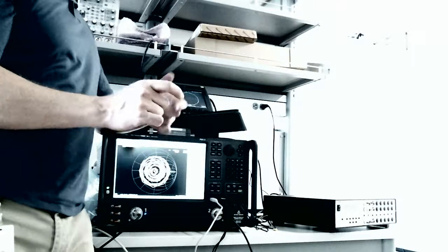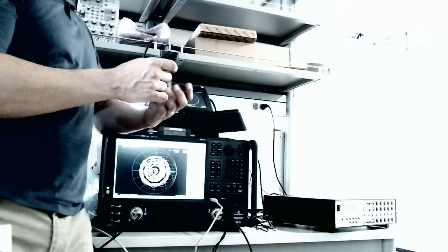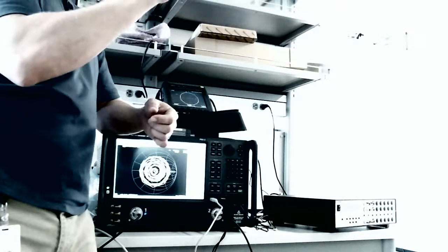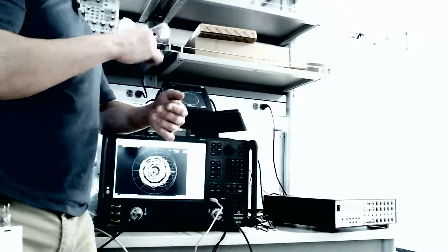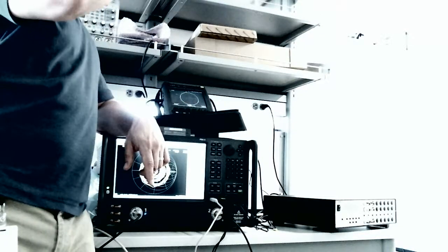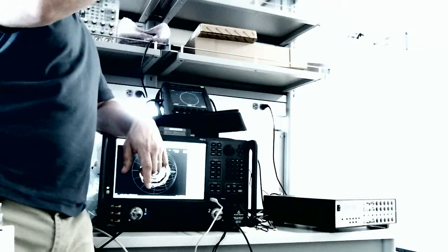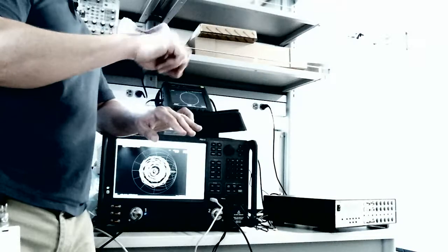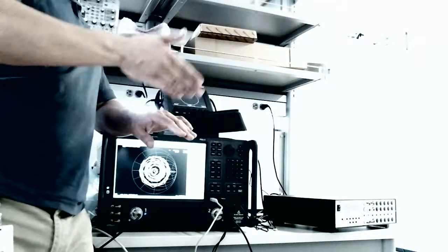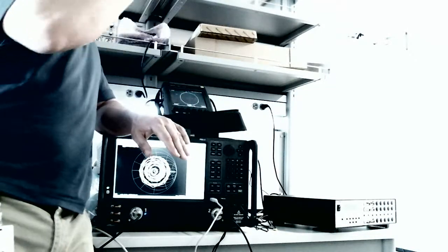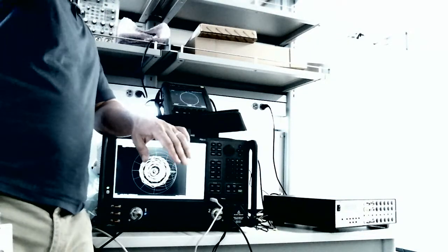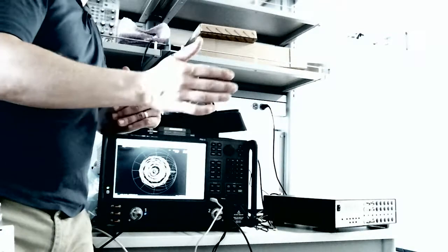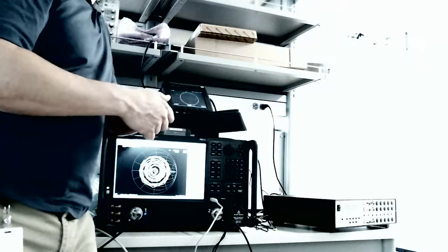Now you know what the impedance is. You give them copper tape that's cut to the right 50 ohm width, and say, design your single stub matching network. They would say, what's the distance I have to be from the load? They put the copper tape down, do some quick soldering, and then trim the copper feed line for the length of the stub until they get the right match. That's a super easy lab to do single stub impedance matching.